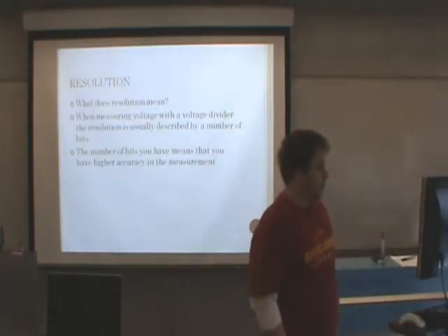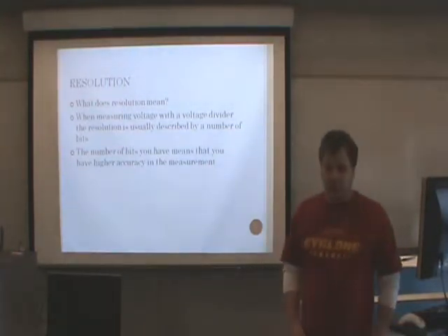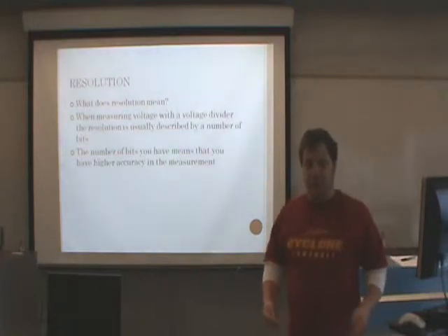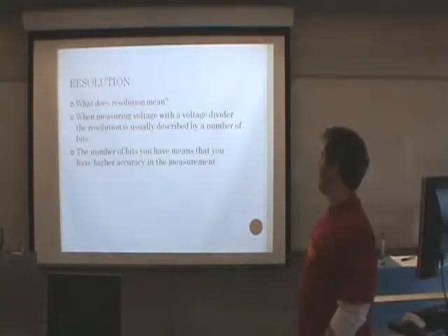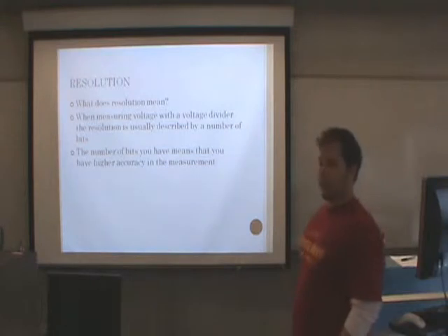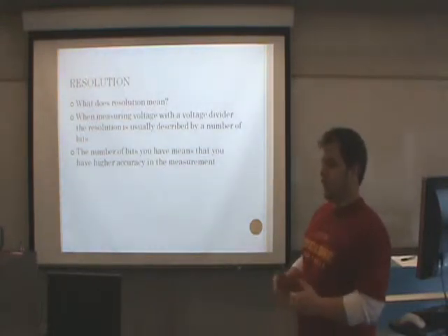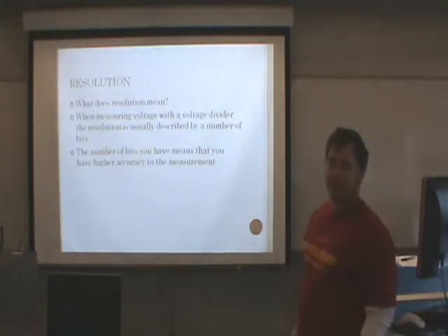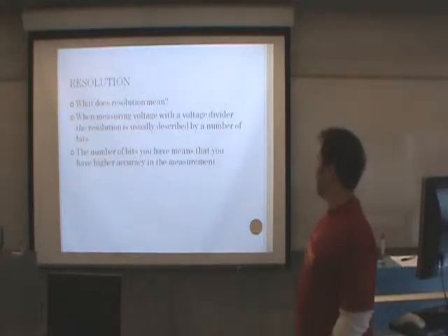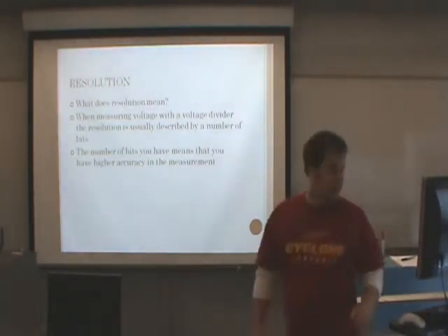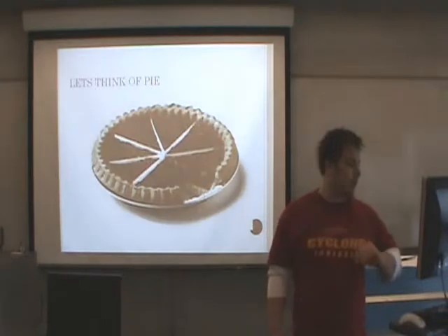Resolution. Resolution is something that's defined by your particular conversion chip. When you're looking for a chip, you'll hear 8 bits, 10 bits, 12 bits. That's describing the resolution. And the more bits of resolution you have, the better your measurement's going to be.